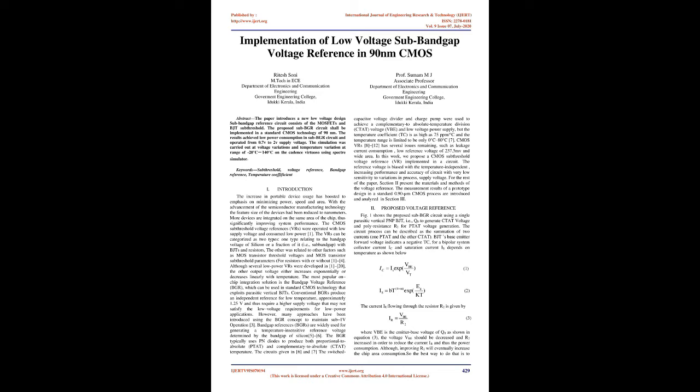The simulation was carried out with supply voltage variations and temperature variation in the range of -20°C to 140°C on Cadence Virtuoso using the Spectre simulator. Keywords: sub-threshold, voltage reference, bandgap reference, temperature coefficient.